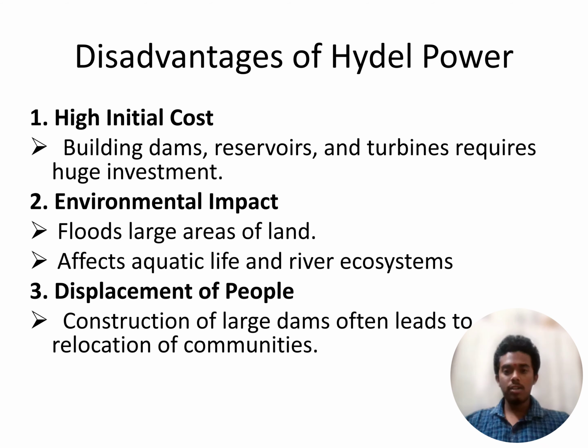And next, disadvantages of hydel power. High initial cost: building dams, reservoirs and turbines requires huge investment. Environmental impact: floods large areas of land, affects aquatic life and river ecosystems, and causes displacement of people. Construction of large dams often leads to relocation of communities.